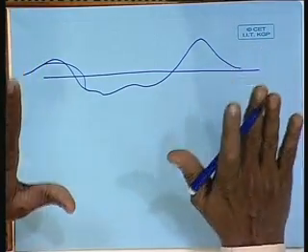What you see when you are standing on the ship and looking behind is primarily the divergent waves created by the forward wave system. Please understand that the other wave systems coming behind the forward wave system get affected by it, because the water is already disturbed. So, the waves generated aft of the forebody get disturbed, and the waves may not be so easily diagnosed.